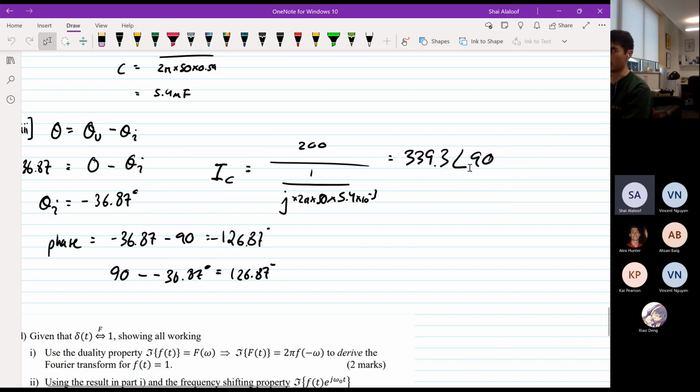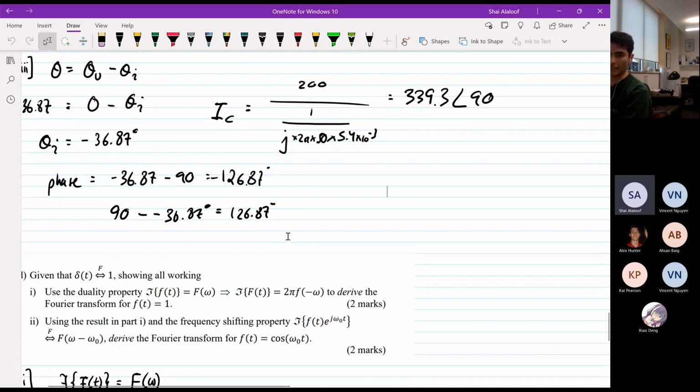That makes the most sense to me. I think if you look at the previous slides, you'll find that it would say the same thing, right? So it's 90 degrees out of phase with the source voltage, and the source current will also be some degrees out of phase. And then you're just doing 90 minus that. Yeah, that's it. Zero point is your voltage. And that makes sense because with the power correction stuff, you always get taught that voltage is the reference. So that actually does make sense. I think problem solved then.